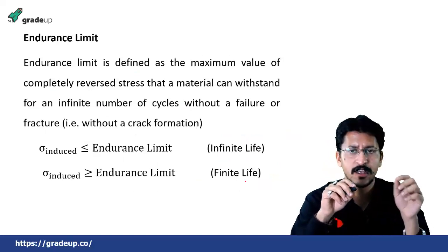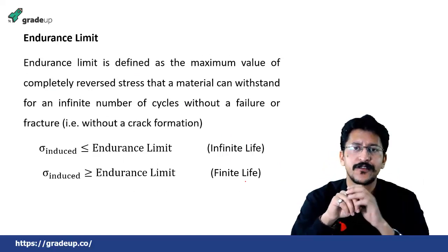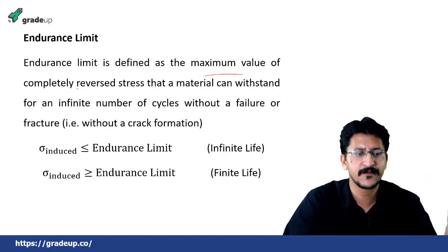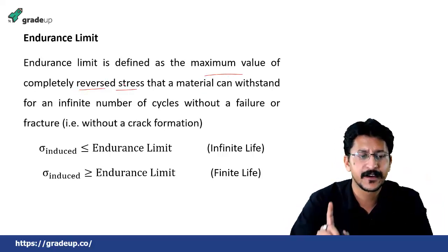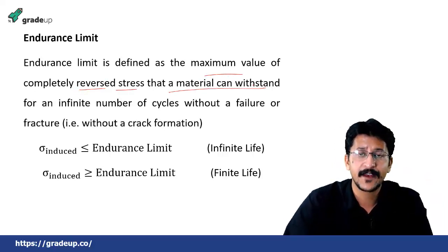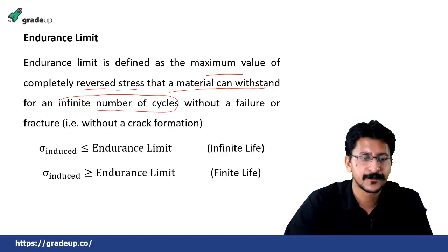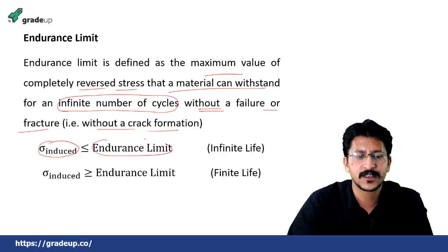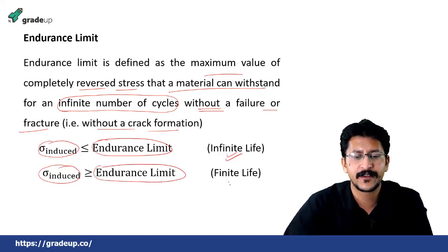Then we saw that the failure stress in the case of fatigue loading is the endurance limit. So what is that? Endurance limit is defined as the maximum value of completely reversed stress that a material can withstand for an infinite number of cycles without a failure or fracture, that is without a crack formation. So if sigma induced is less than the endurance limit, then it is infinite life, and if sigma induced is greater than the endurance limit, then it will be finite life.